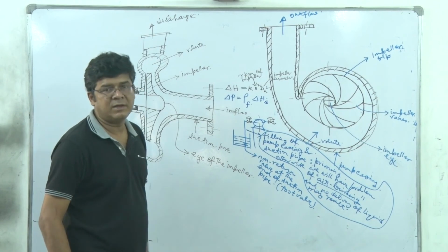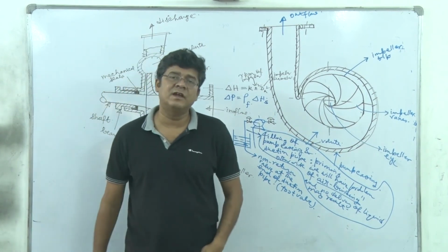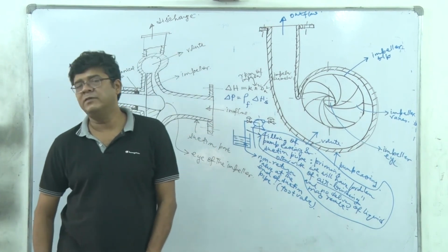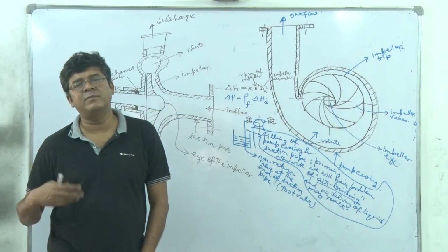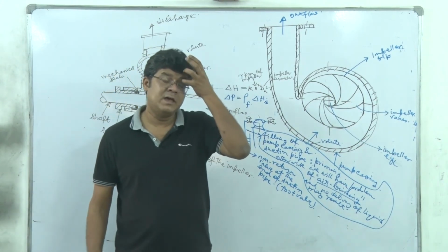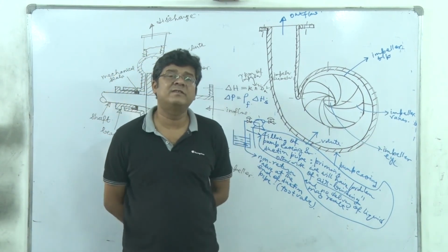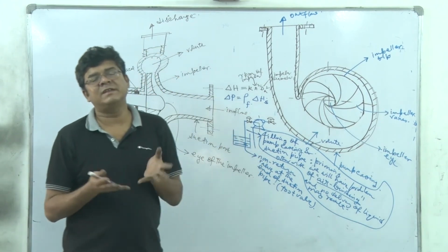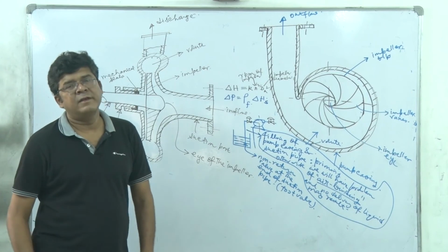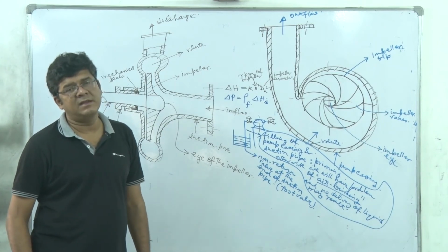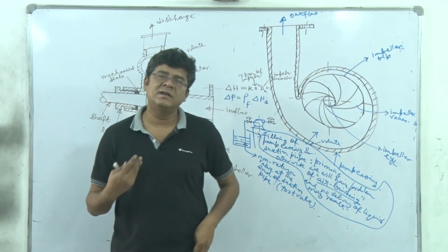anytime without priming. But for large industrial pumps, where we may be transporting a liquid which readily forms deposition, like tar or crude oil, if you keep the crude oil or tar within the pump casing, it will deposit and clog, right? So that's why it is to be continuously primed. And for priming large pumps, there are different strategies.